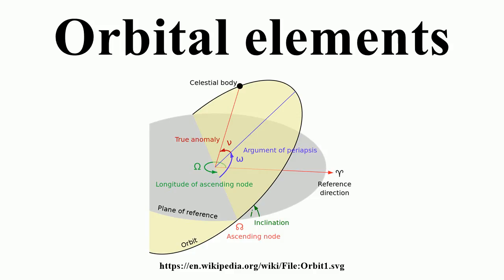Real orbits have perturbations, so a given set of Keplerian elements accurately describes an orbit only at the epoch. Evolution of the orbital elements takes place due to the gravitational pull of bodies other than the primary, the non-sphericity of the primary, atmospheric drag, relativistic effects, radiation pressure, electromagnetic forces, and so on.